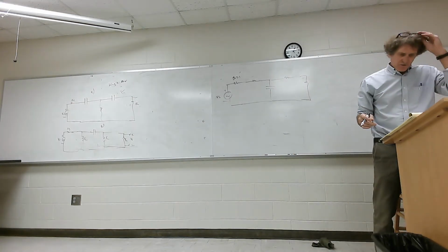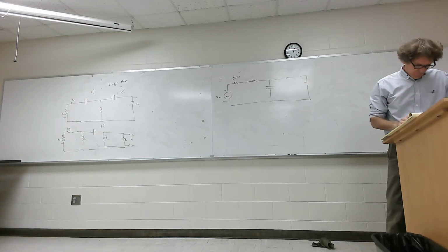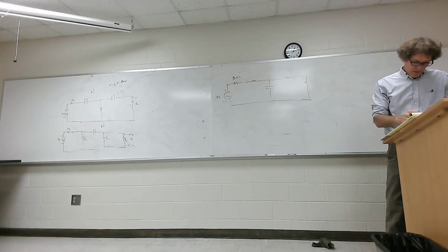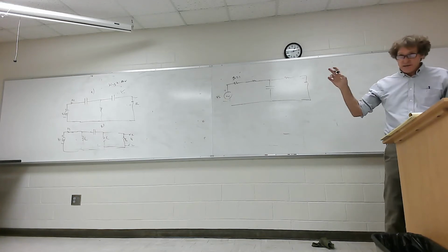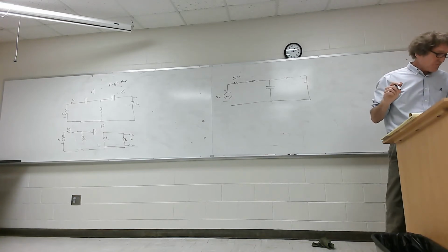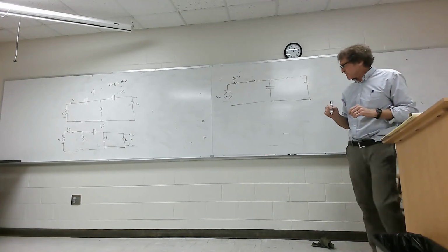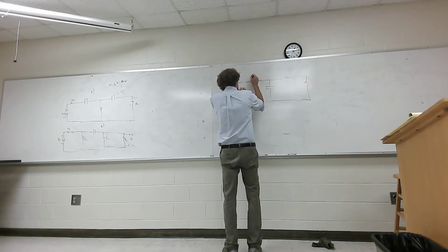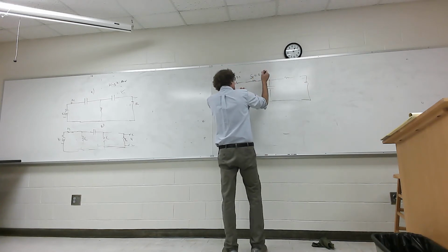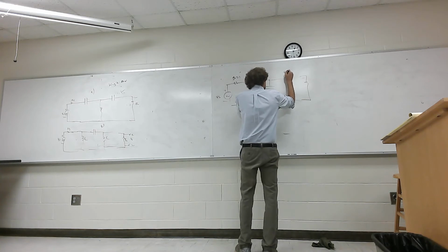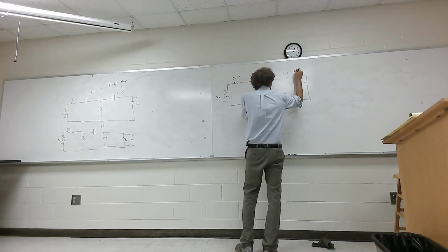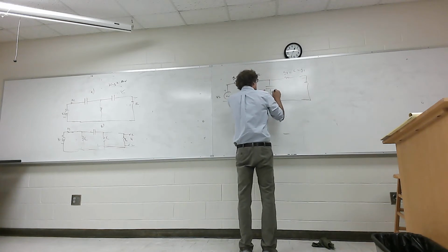So, for this one, might as well do the same thing. Actually, I think this is example 10.16. Modify example 10.15 that we just did to design a third order high pass filter with 1 dB of ripple at 2 gigahertz. So all the conditions from the last one are going to be used here. And he shows on page 588, he starts with a low pass filter. And here, this value of G1 is just the L. G3 is equal to, L is equal to G1, and here, G2 will be capacitive.